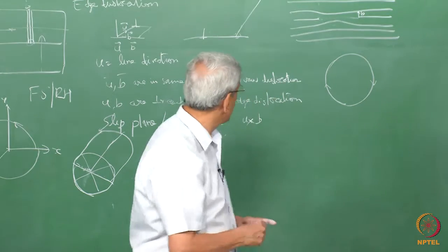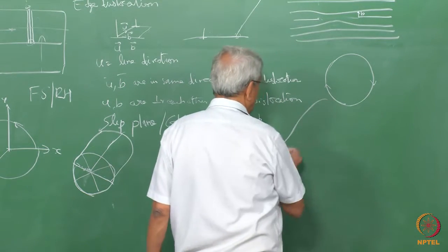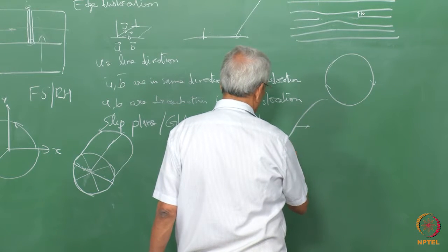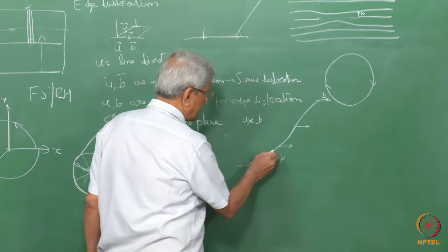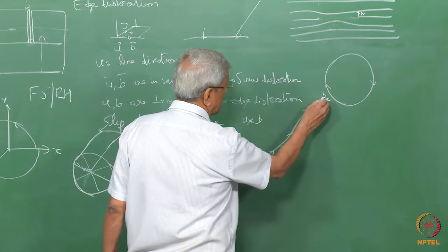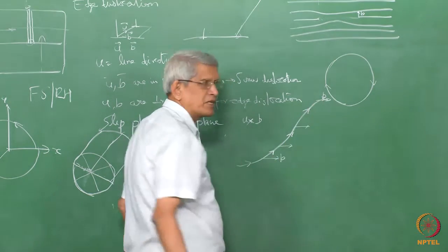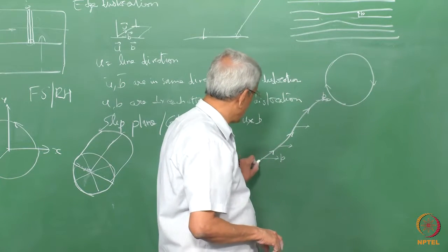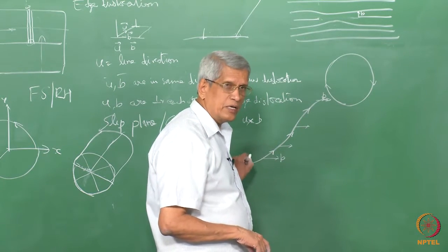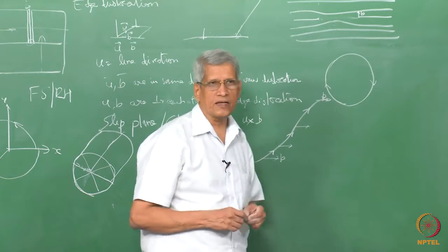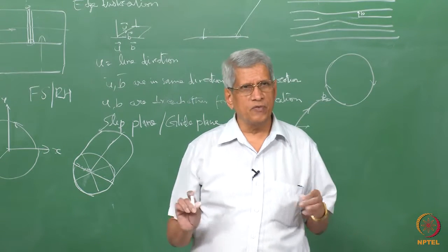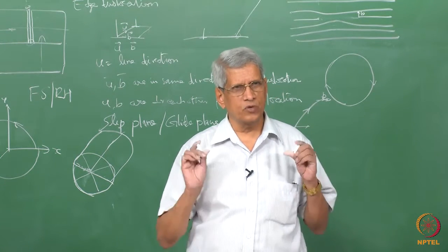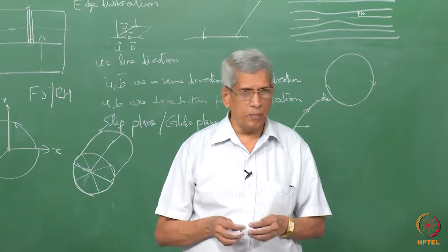It can happen in so many cases, a dislocation line which we see, but the Burgers vector is going to be in this direction. Like here also the Burgers vector is in this direction. So if you see it, this is the line direction. So here the line direction and Burgers vector are in the same direction. There can be some other position, it could be inclined. So these types of dislocations are called mixed dislocations. This is the type of dislocation which we normally see in most of the material. It is only the mixed dislocation which we see.